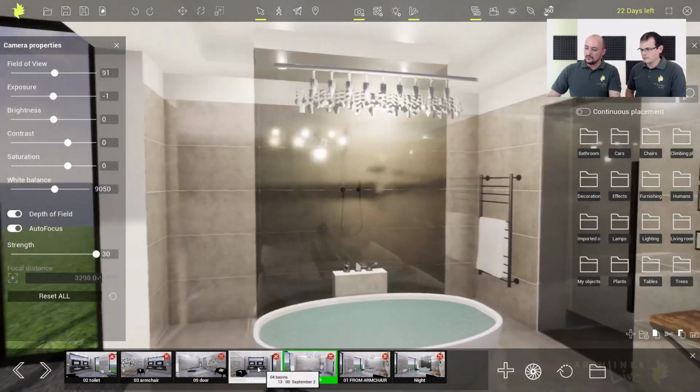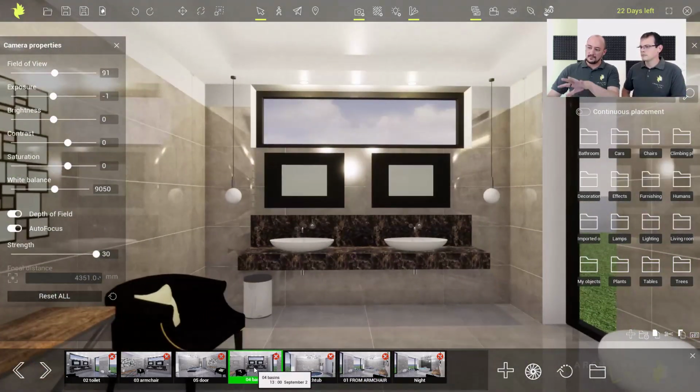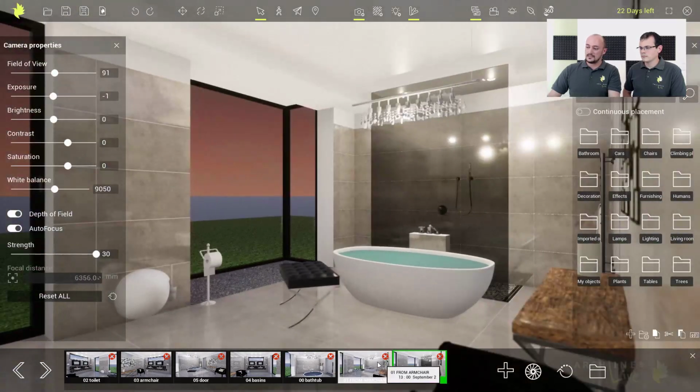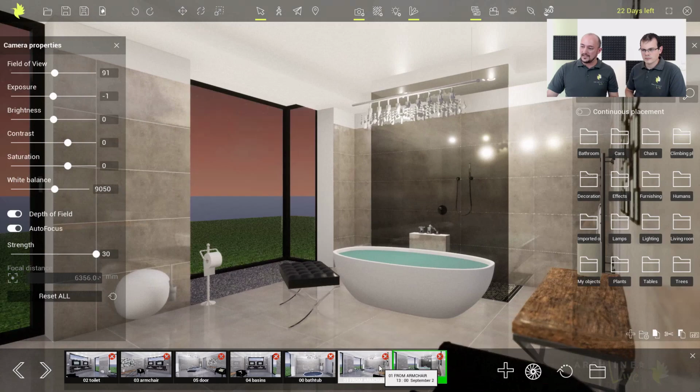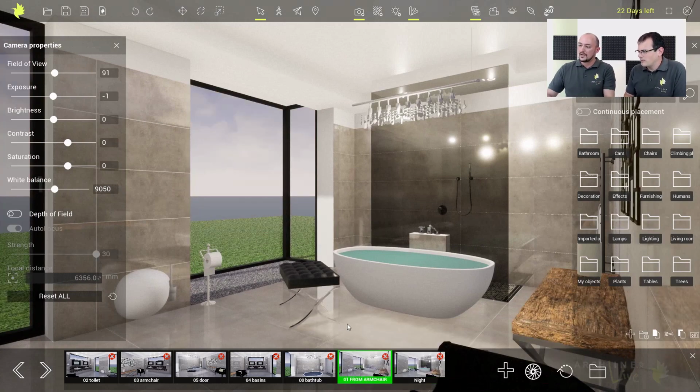And whenever I move my mouse, the views obviously change. The camera angle is changing, but the rest is kept, because I just decided to do so. So I have all the same warm tone, white balance everywhere, depth of field enabled, and so on. And should I have another view where I don't want, for example, depth of field or any of those, I just go there, disable that, and on that view I have that disabled, but on the rest, everything is in effect. How about we add some customized elements, let's say a few items in here?